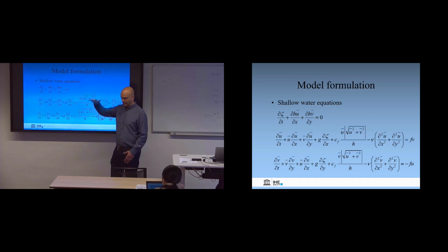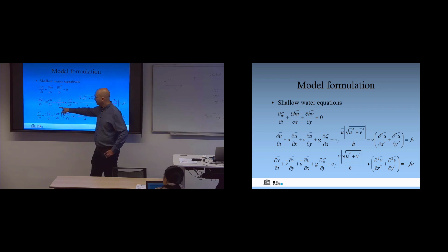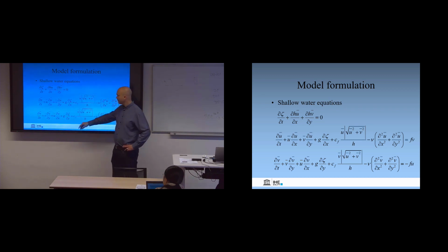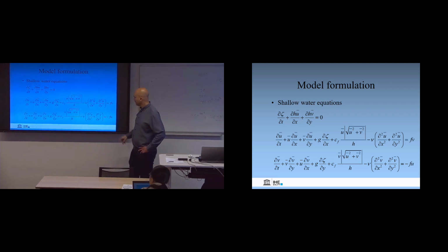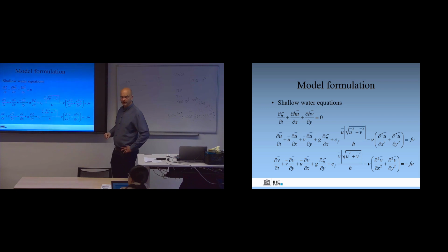If the water level goes up, there must be water coming into that cell. And this is then the inertia, time derivative, the advection. This is the advection terms, the pressure terms, water level, friction, and viscosity. And this is then Coriolis force for the larger systems.